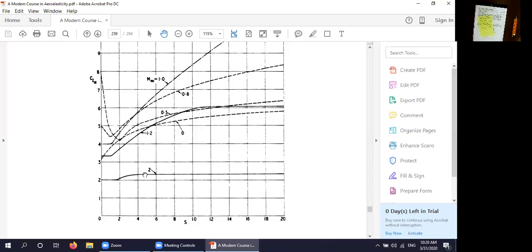And if I looked at a Mach number like 4, all of these results, this factor of 2 would go down to a factor of 1. And then the difference between this curve and this horizontal line would be even smaller. And in the limit of a high Mach number, you get basically just a horizontal line. The result wouldn't depend on time at all at high Mach numbers, according to this potential flow model.